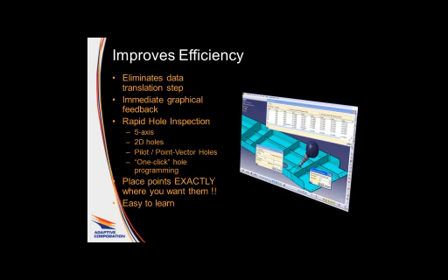I will show you during the demonstration how quickly we can move around the solid model to program virtually any feature. Also control the motion of the probe. You can place points exactly where you want them based on engineering or customer requirements. We can also use other CATIA features like planes and curves to create our inspection points. Also, the V5 CMM Planner improves QA department throughput since we are creating CMM programs offline without tying up the CMM machine.